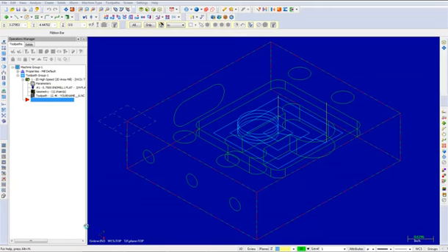In this video, I will show you a 2D high-speed area mill. In this step, you will learn how to copy a toolpath and reselect geometry. The main advantage of copying a toolpath is the parameters for the first toolpath remain intact for the second toolpath. First, to remove the toolpath display from your screen, press Alt-T on your keyboard.